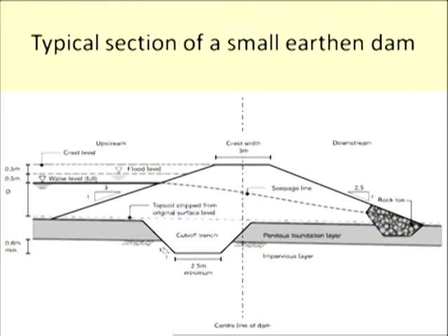In the case of this earthen dam, we have to keep the slopes gentle, as we are using locally available material. So you look at both slopes. This upstream slope is 1 vertical to 3 horizontal, and here the downstream slope is 1 vertical to 2.5 horizontal. So these slopes are quite gentle. The upstream slope is gentler compared to the downstream slope, and this is the core or the section body of the earthen dam. We have to put clay, locally available soil, here in layers.